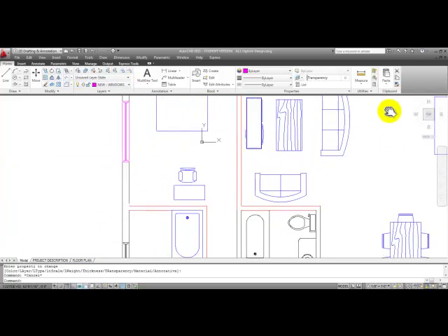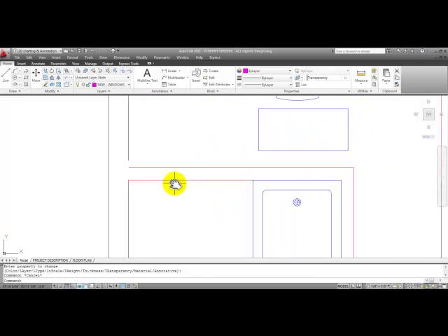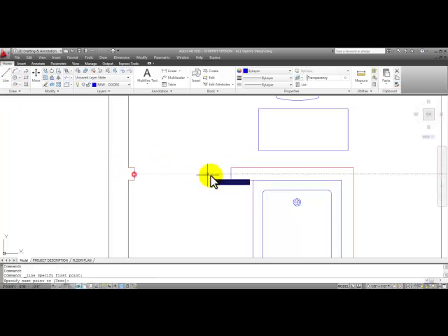Use the same concept here to develop possibly a sliding door. You can select here this wall and pick inside the grip to clean it up, clean the corners up, then draw lines to represent your door and trim, press enter, and cut out what you don't want. Draw maybe a line here that represents the door and the track below.